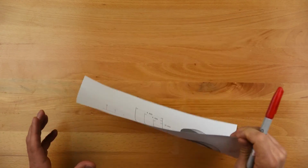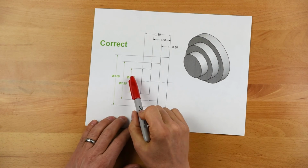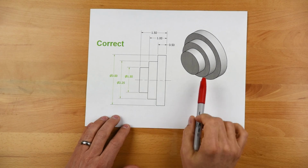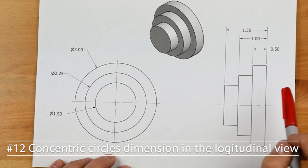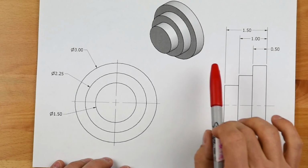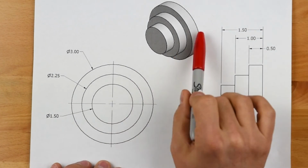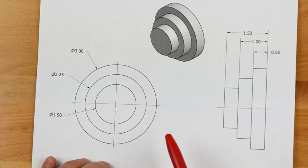And so what we really want is to have these staggered so we can kind of see what's going on. When we are dealing with the shaft, in this case, although a very short and stubby shaft, we want to, again, dimension our diameters on the view that shows us those diameters the best.